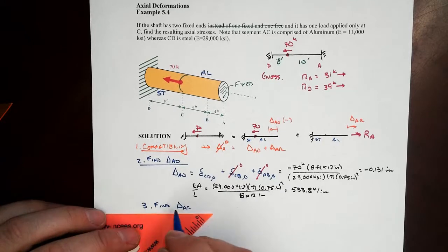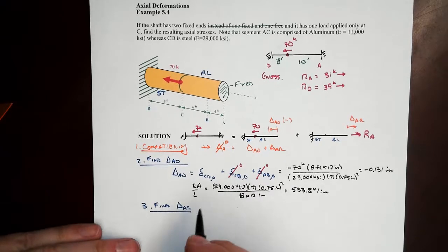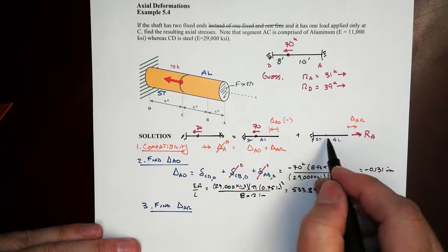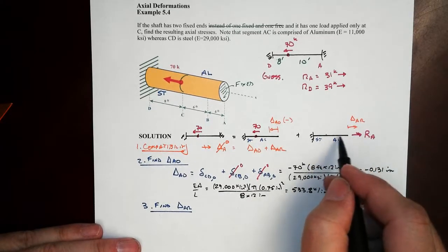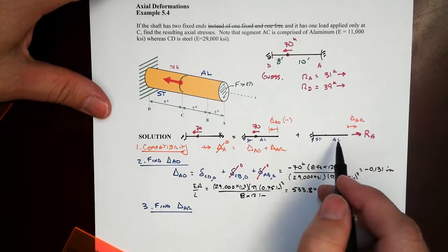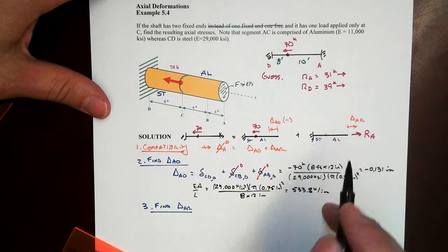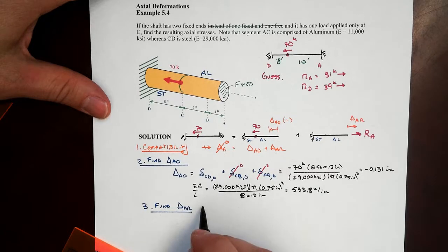Well, let's find our displacement to get things put back. That will only be in symbolic form, and it'll get a little kind of complicated, because we have two different materials. So we'll have a constant axial force in both, a common axial force, but not common stiffness, because the material changes.